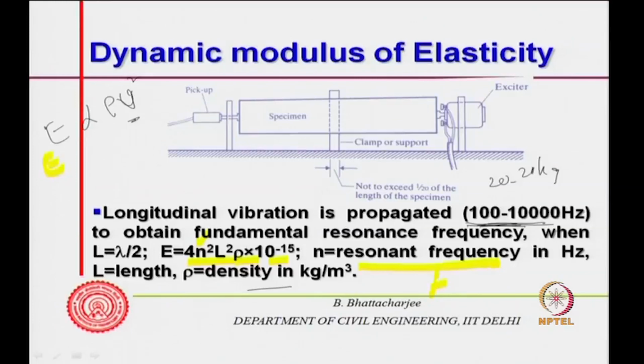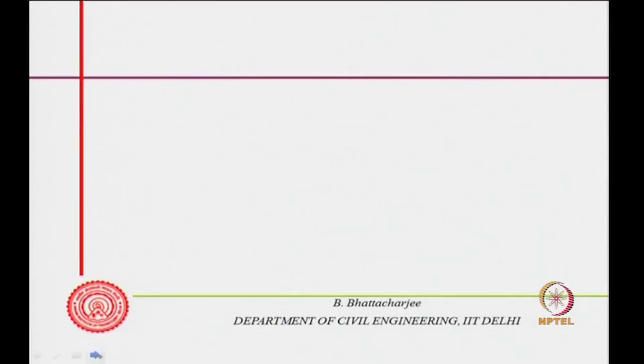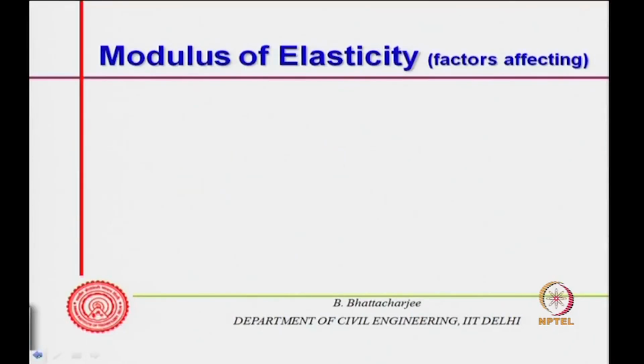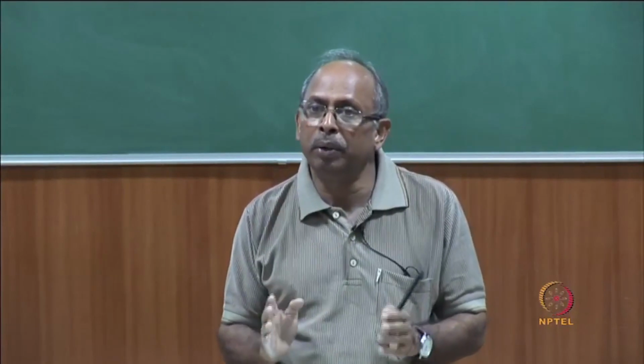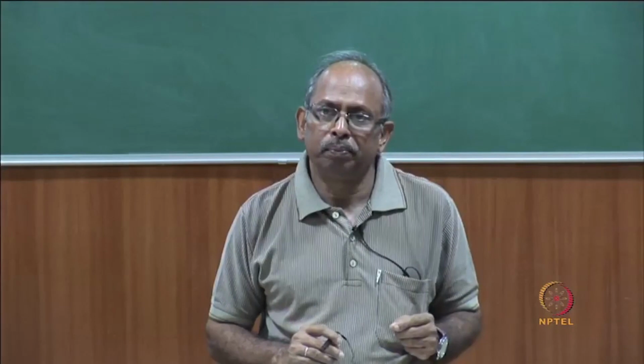So, this is not ultrasonic, this is actually sonic excitation you provide, and then find out from this the modulus of elasticity. So, this is how we find the dynamic modulus of elasticity, and we said that the dynamic modulus of elasticity is the initial tangent modulus, because no cracks have occurred in an uncracked specimen. Usually these values are higher.